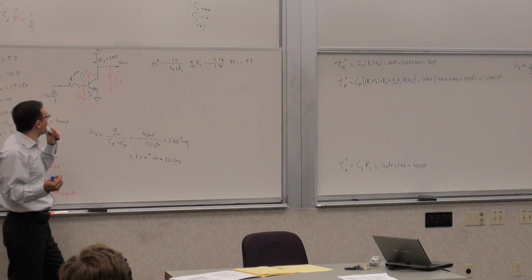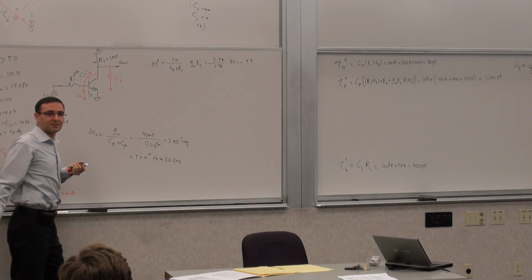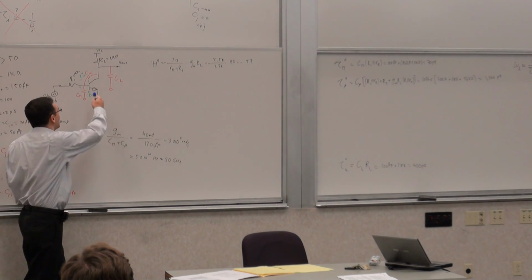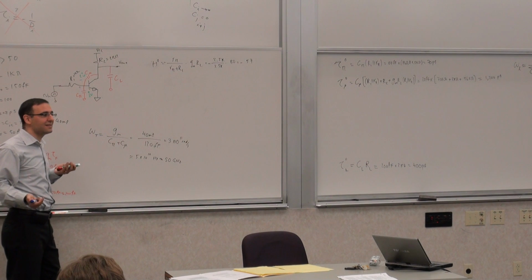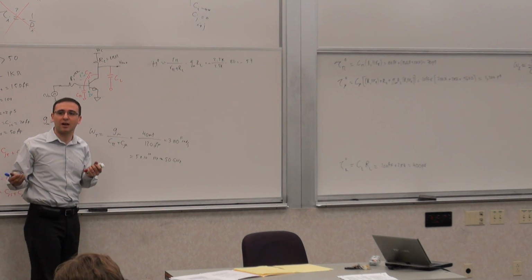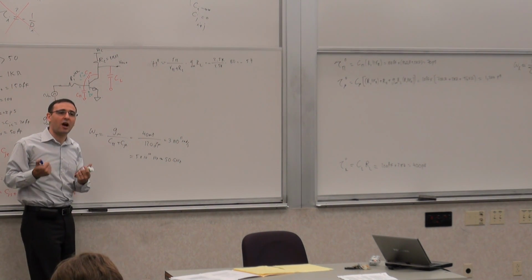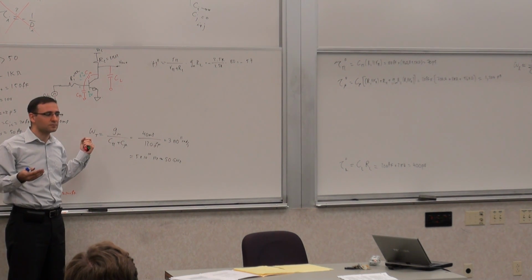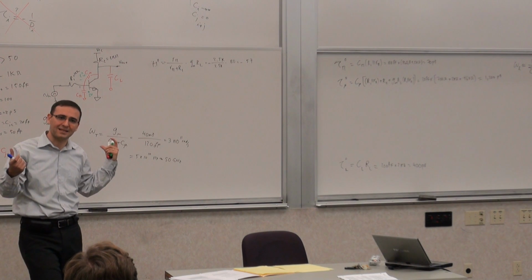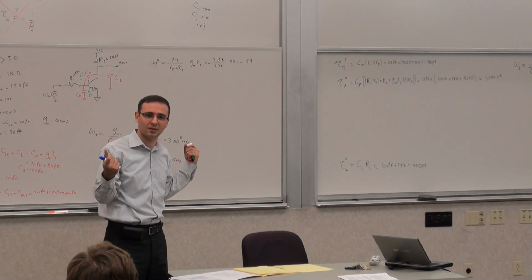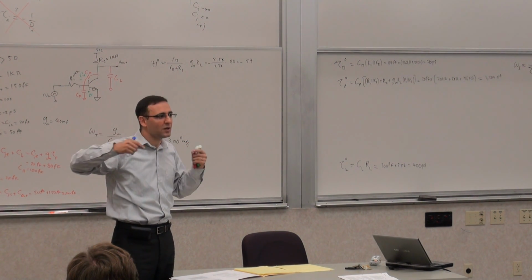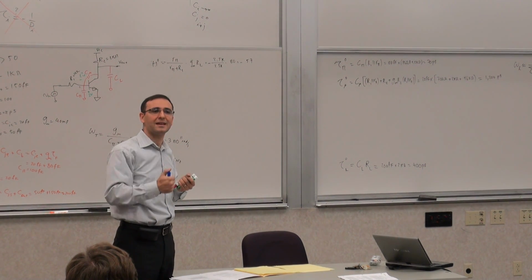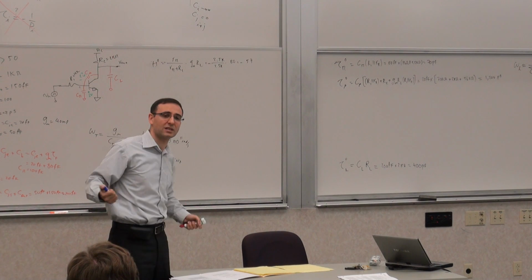Here. Well, maybe you shouldn't get the gain across here. Right? The problem is that you have a lot of gain across this capacitor. Maybe you should get the gain across somewhere where you didn't have a lot of capacitance. You remember that common gate or common base that we just talked about a few minutes ago, that one didn't have any dominant time constant. Why was that? Because there was no explicit capacitance between its input and output. So maybe we can get our gain out of the common base, but the problem with the common base